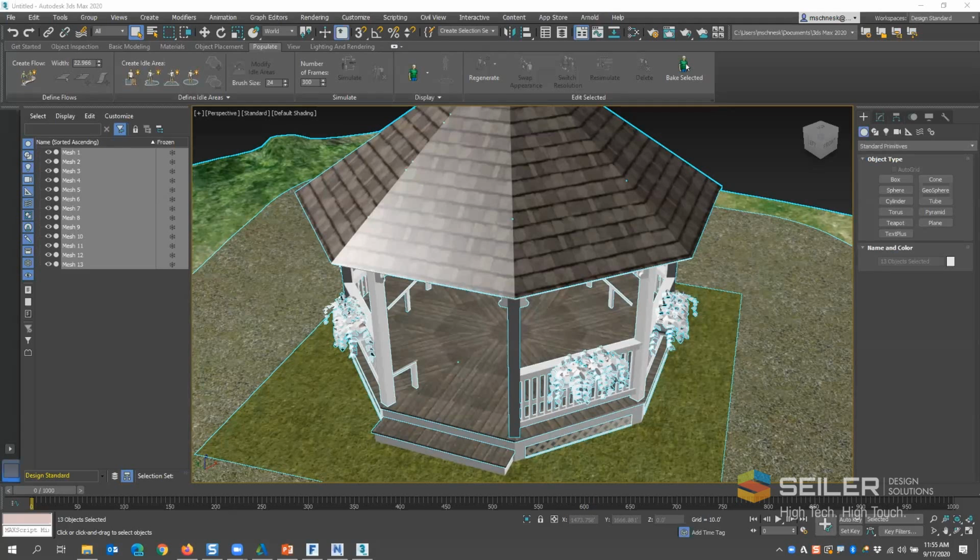I have another webinar where I did an export from InfraWorks into the 3ds Max Interactive VR, and there was a shift that had to be made in 3ds Max, and you have to note that shift when you import a particular file. If it's shifted far enough, it'll give you a message that shows how much X and how much Y it's shifted. You may have to take that into account when you bring it back in or export it out.